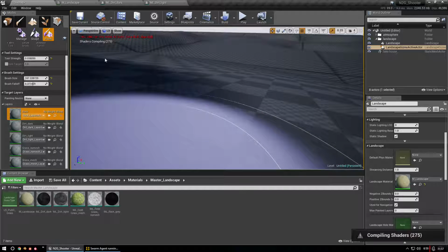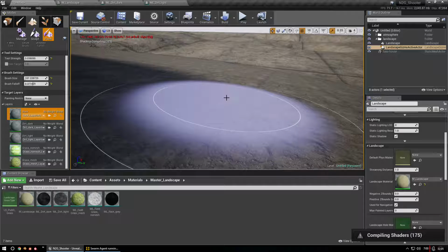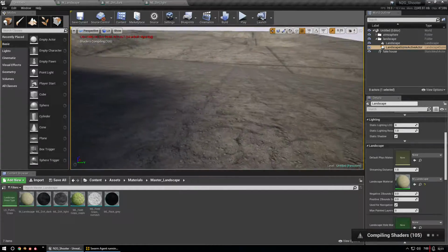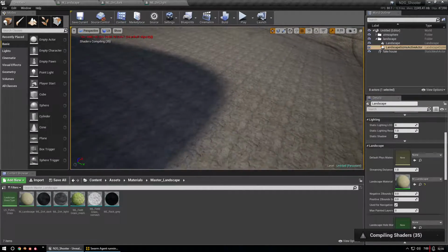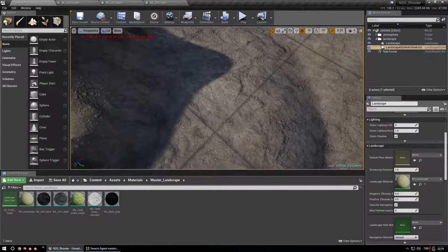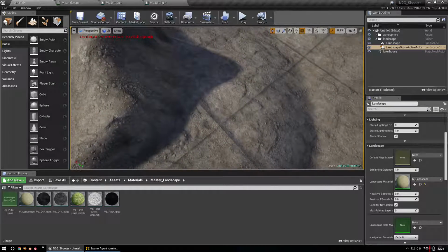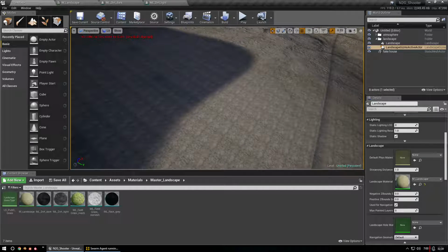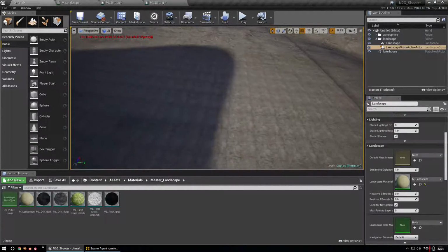They take a while to do, but until those shaders are done, we gotta wait. That's really why I didn't want to get into this, but let me just pop out of that real quick so I can get my crosshair back. But yeah, I mean, you can actually see it. See that tile? That's just ugly. So as I fade out, I pull away, I'm stuck at that max set 32 that we set in the default material function. But as I pull back in, the close UVs is governed strictly by that landscape coordinates node in the actual landscape function that I just changed to 2.